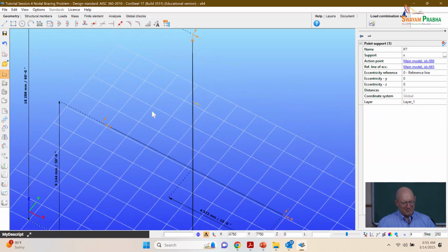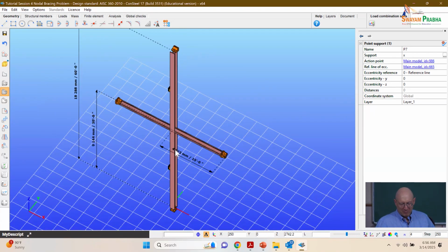So remember, with a situation like this, we might need to worry about torsional bracing or torsional buckling, right? Again, we're spanning 60 feet, except we're grabbing the middle of this, and it's major axis bending in and out of, or normal to, this wall of the shaft. Our flying beam is in major axis bending to try to provide support to the middle of the column. Okay, so let me ask you, what type of bracing is the flying beam providing to the mid-height of the column? Nodal, or point, right? Okay, this is a good example of a nodal brace or a point brace.